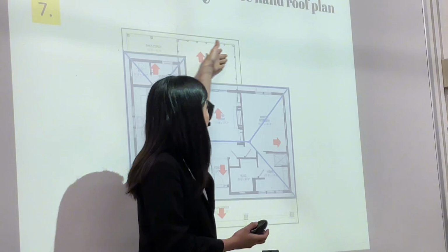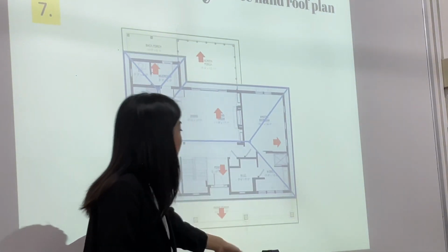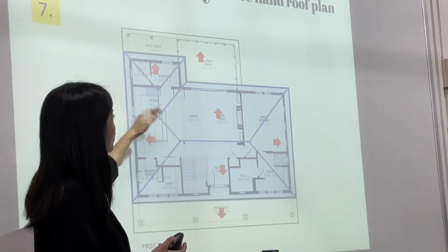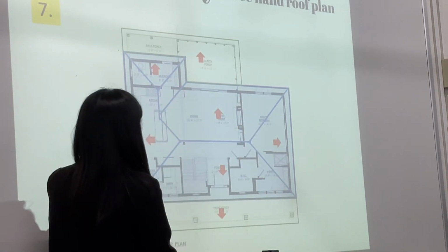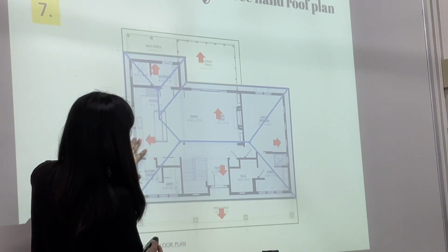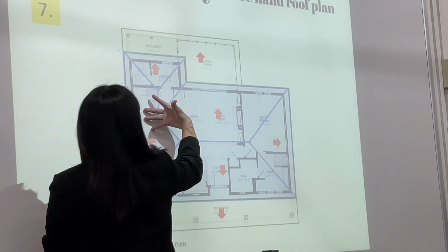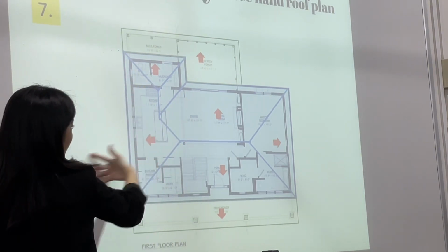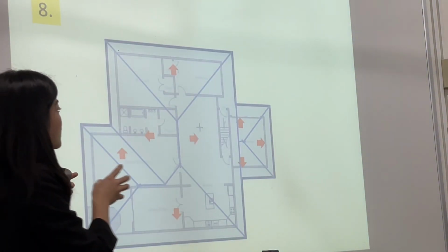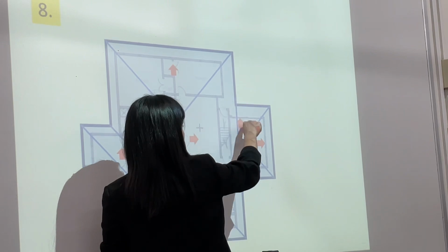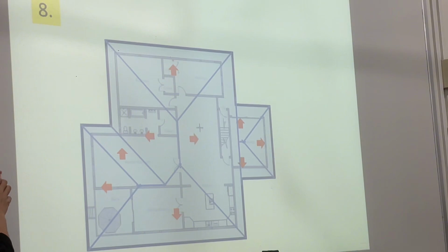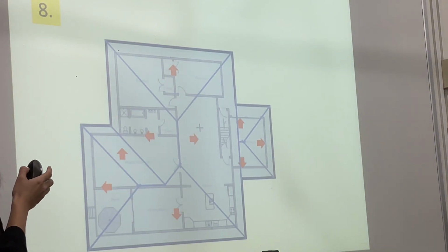You can go there, it's up to you, as long as the roof goes in one direction only. And a common mistake also, this is the major roof, so maybe you put 45 degrees here too. Again, useless line. You have to erase that. Realistically, all the rainwater will just flow here. Okay? Can you imagine it now? For number 8, since this is separate, it's up to you, even if you put 45 degrees there. That's okay too. Yeah, you can. Questions?